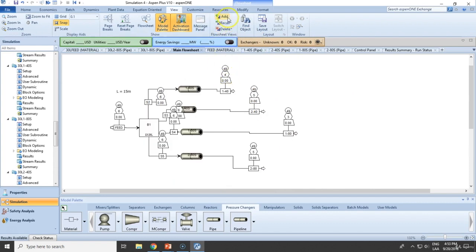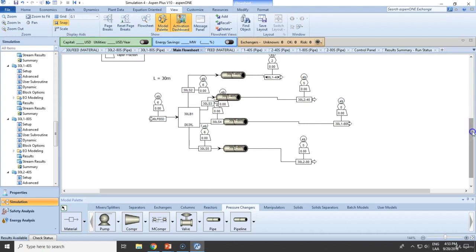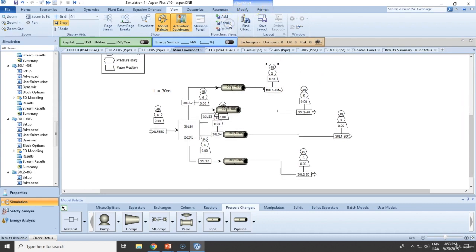So we got 4, and in 30 meters we get this one right here. We are having a total pressure drop here. So what's going to happen is that you need to increase the pressure, so you need to add a pump because there is no more pressure to push the water, which is very interesting, how it is the one with the greatest pressure drop until eventually you will need to add a pump to continue this flow rate.